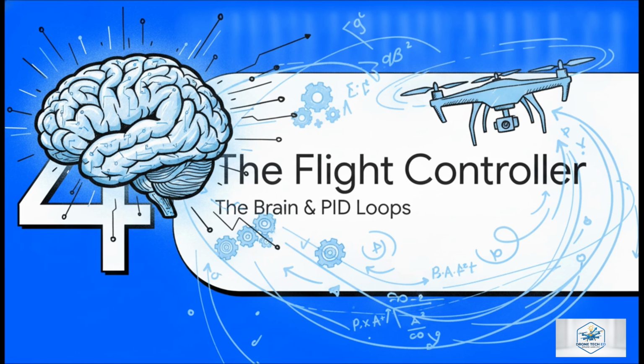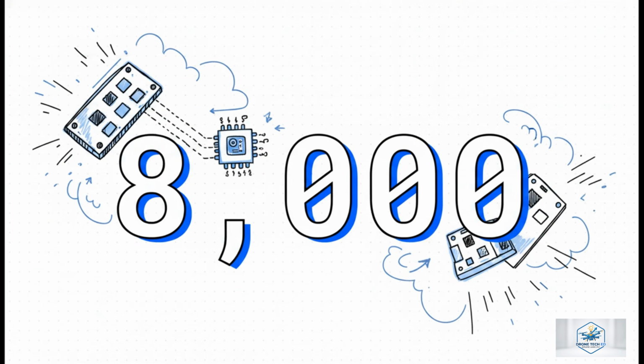Let's move to part 4 and see how this all builds together: the flight controller, the brain, and PID loops. This is the brain, the central processing unit running the high-level math that actually keeps the aircraft stabilized in the sky. High-end flight controllers are running their closed-loop stabilization math up to 8,000 times every single second. That's 8 kilohertz. They do this by rapidly reading spatial data from microscopic MEMS gyroscopes right on the board, detecting even the tiniest gust of wind way before the human eye could ever perceive it. It's literally reacting faster than a human reflex.